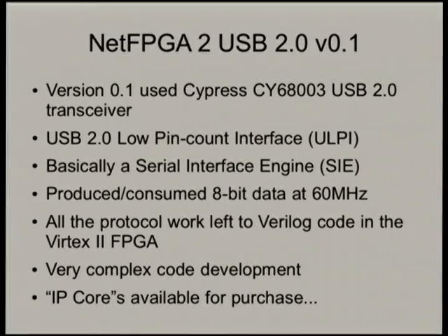It basically relies on implementing most of the USB protocol stack in FPGA code. There are some implementations available, especially on the OpenCores website, the open FPGA type work that people have been doing. But it was still going to be a huge amount of work implementing an interface using those serial interface engines and then putting all of the USB code into the FPGA. So we could have bought some IP cores for using with that, but instead I decided at some point to go back and try a new design.